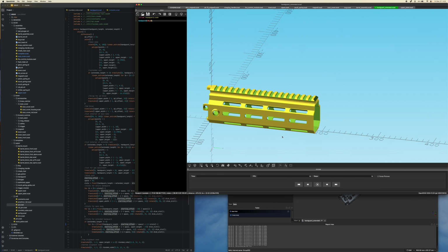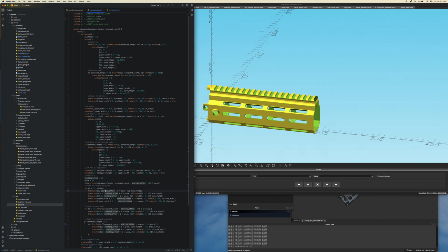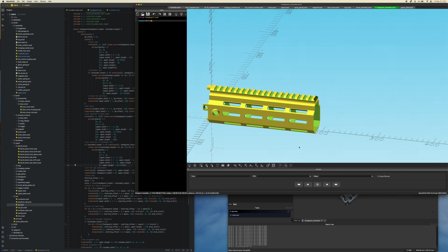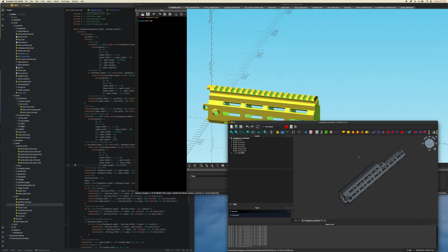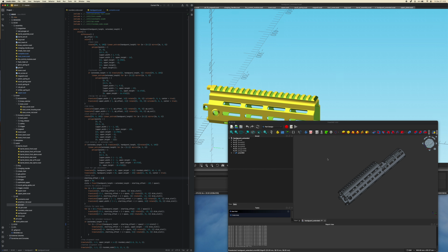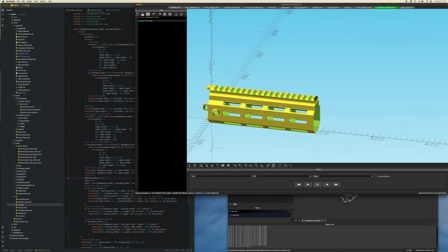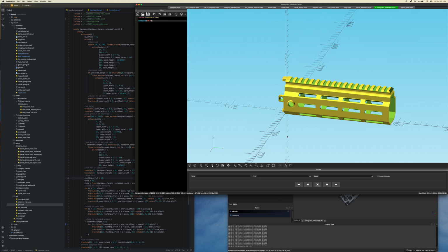So this works fine in OpenSCAD if I don't have these blocks right here, and same for here, for example. But the problem is when you go into FreeCAD, OpenSCAD is going to give you a bunch of issues. OpenSCAD is generally a lot pickier when generating the STEP files than the STLs, so you're going to want to be really careful about writing high quality code to generate those, since what works in OpenSCAD may not necessarily work to generate a STEP file.